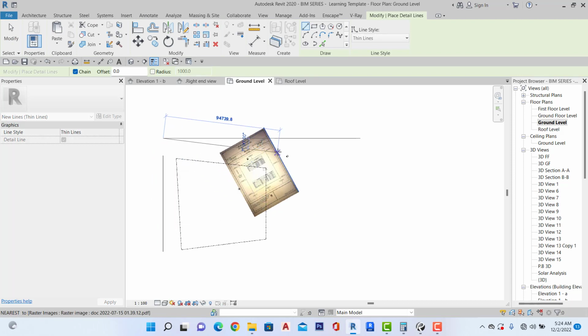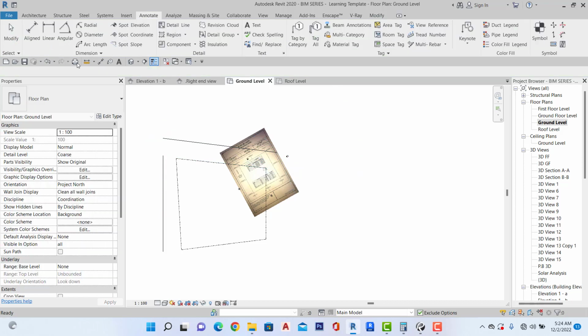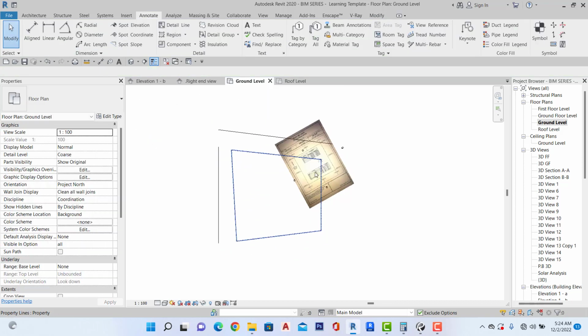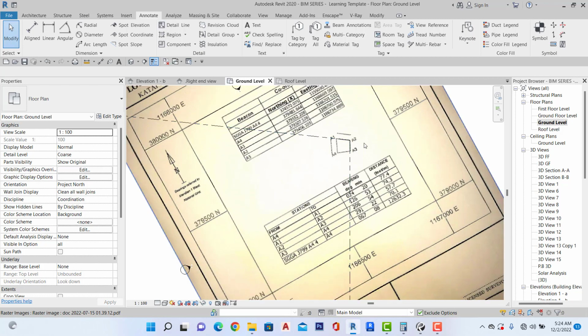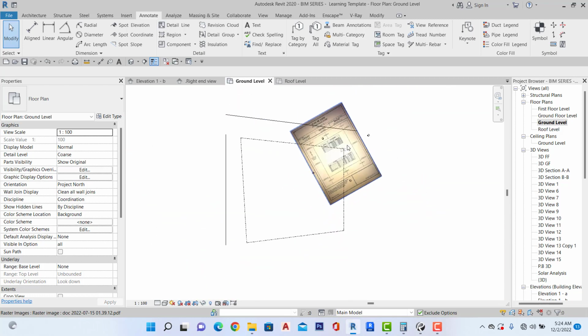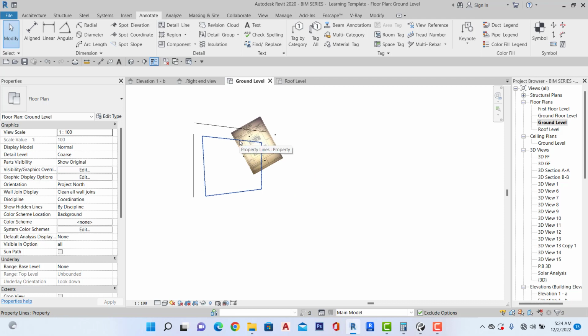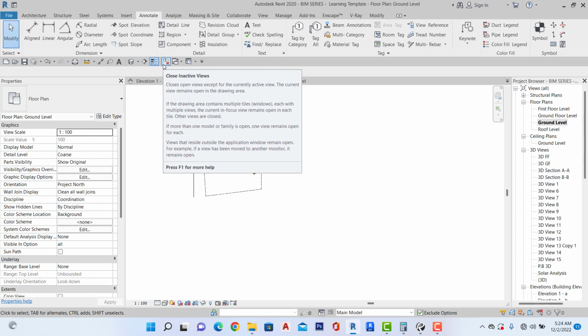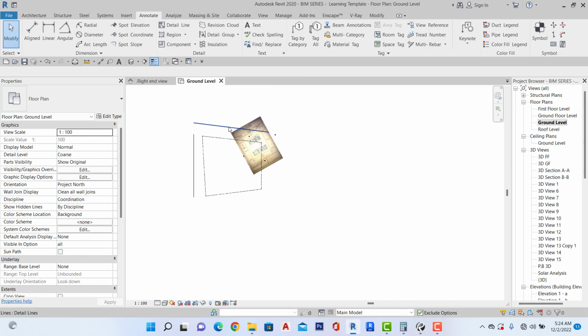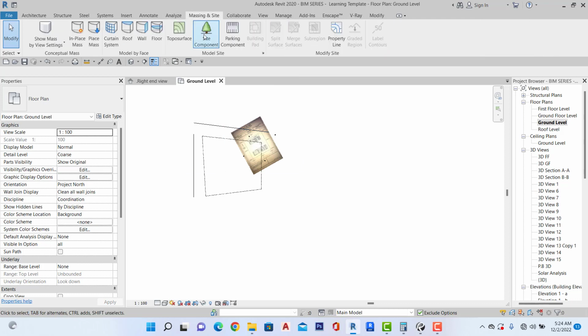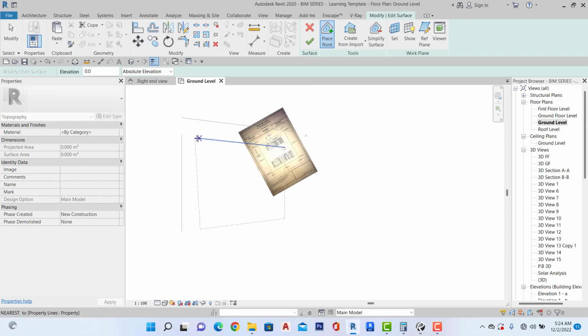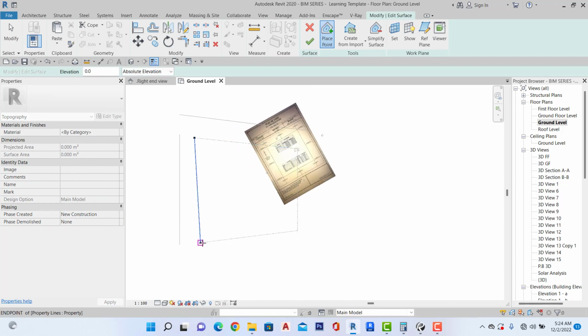and also I'm going to have a road here, right? Okay. So guys, this is how to create your property line by transferring this into this. Okay, so we move on with the planning. We move on with our next step, which is going to be the topo surface. With the topo surface, I'll still come to the massing area, click on topo surface, then place a point here, a point here, a point here, and a point here.